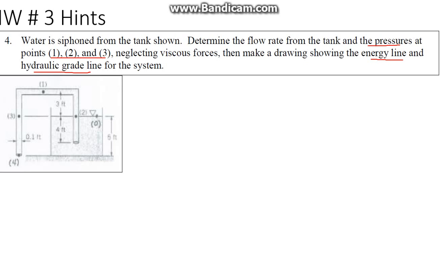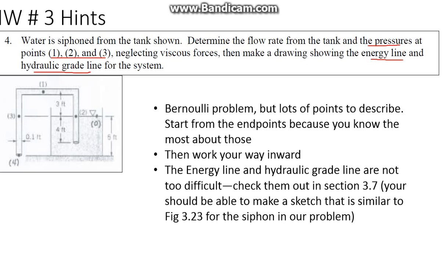It's not very hard, and if you look at that section, I believe it's section 3.7, you can look at the energy line. So Bernoulli problem, lots of points. Start from the ends because that's where you know the most. Remember here and here you have atmospheric pressure, so those are good places to start. And then work your way inward.